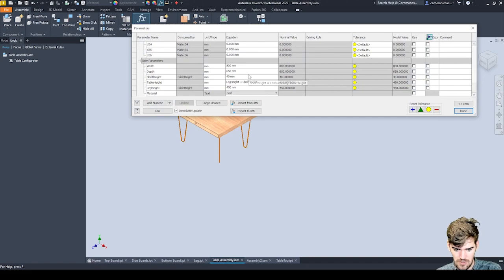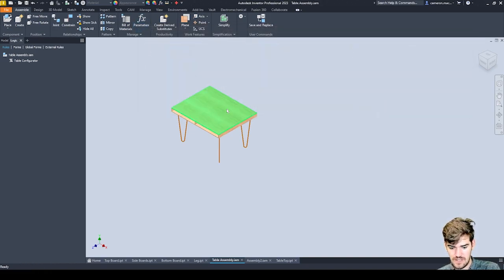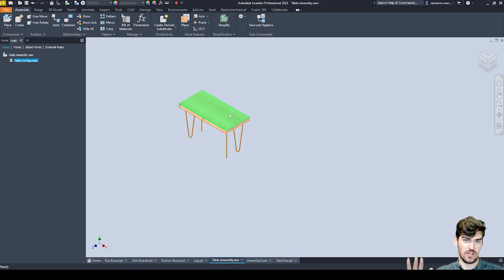But yeah, if we go and have a look in that list down at the bottom and change our depth from 650 to something like 400, hit enter on there, it's changed the value in my document but hasn't pushed it through, and that's what that other little update button does inside of our script. So if I run this rule now, it'll update that value inside of all of the components essentially.